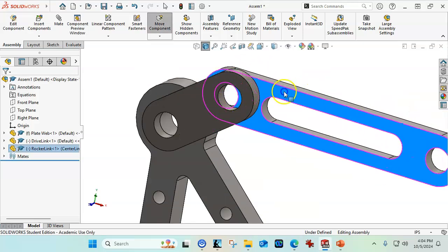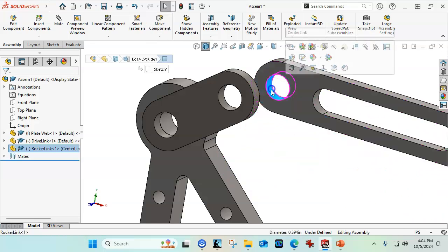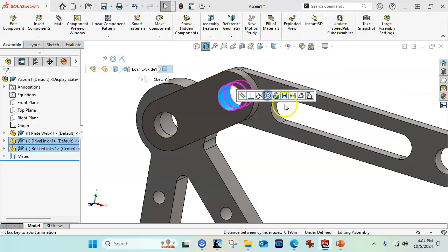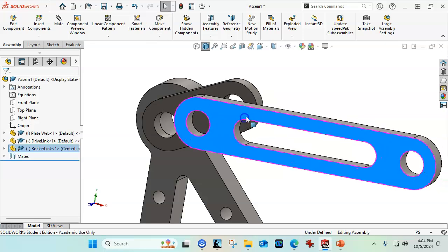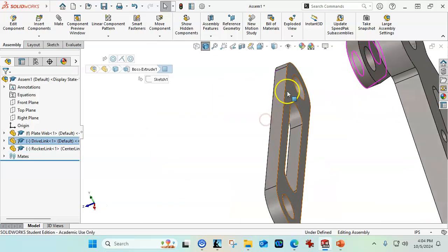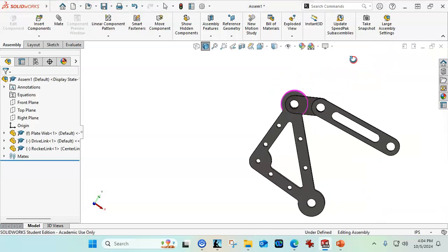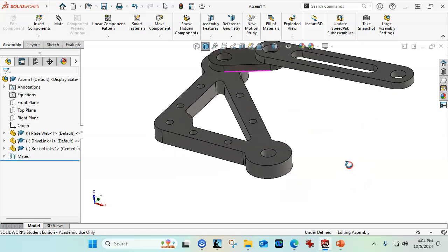And then it didn't do it anyway. So if it's on that side, it's going to run into the plate anyway. So let's go concentric, and the order of the mates isn't really that critical. As long as they get in there, you can put them in whichever order you need.